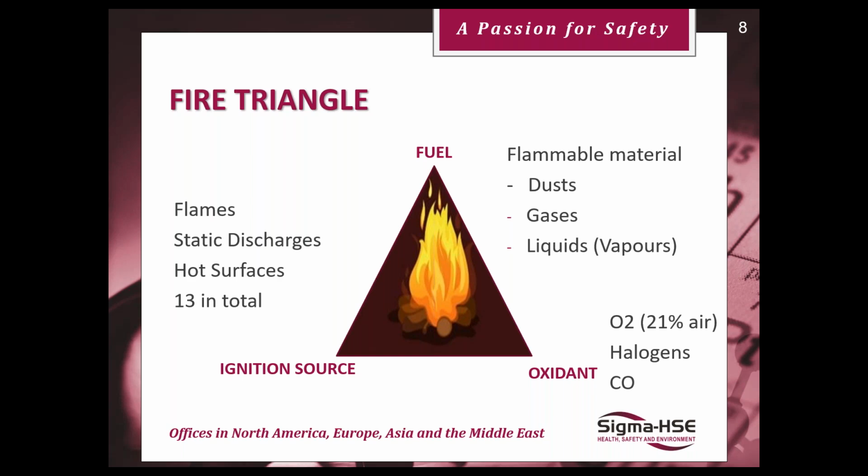But there are many, many other materials, especially in solid form, that can react. Many common materials can react with oxygen and burst into flames. Things like sugar and flour and paper dust and cellulose and all of this sort of stuff. So it's just a chemical reaction, and with all chemical reactions, what we need to make that reaction efficient is good mixing, which is where we're really looking at a gas-gas or vapor-vapor reaction. And we need to impart sufficient energy.